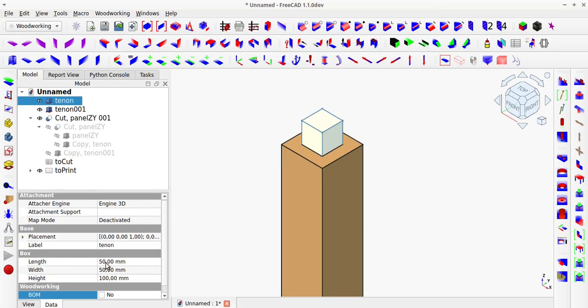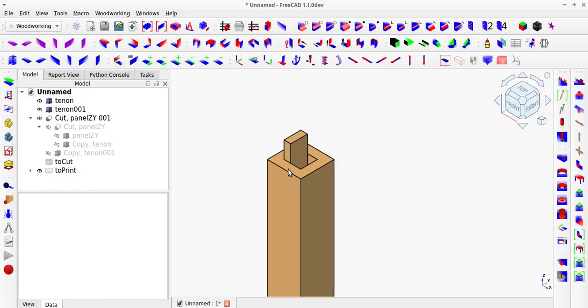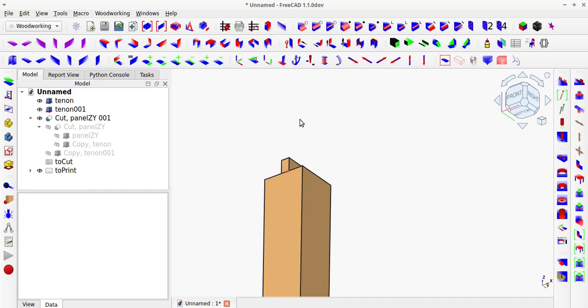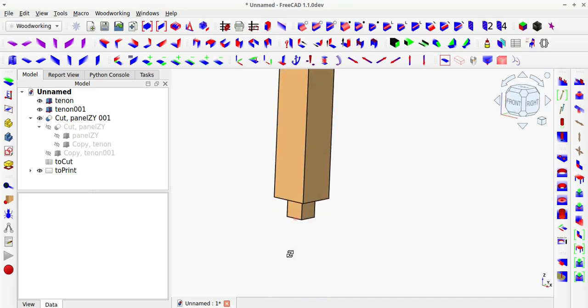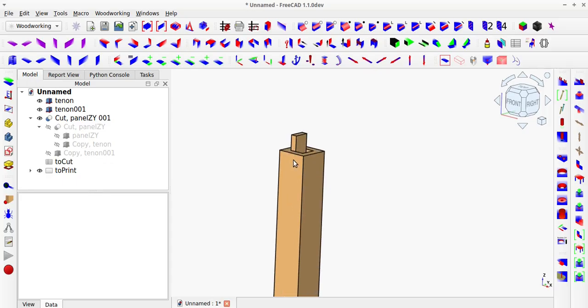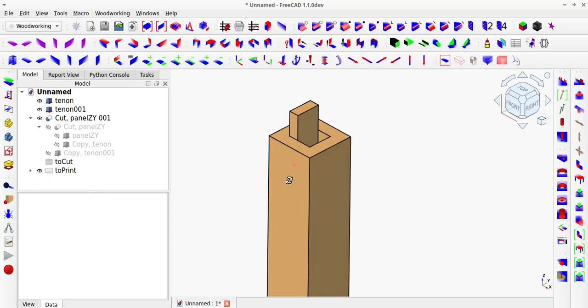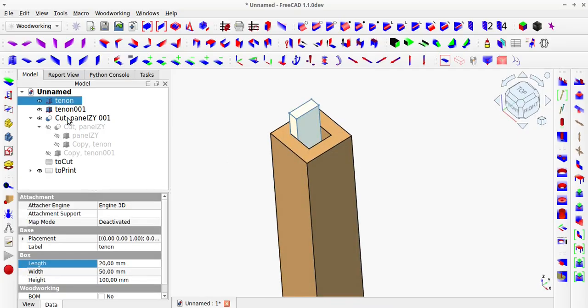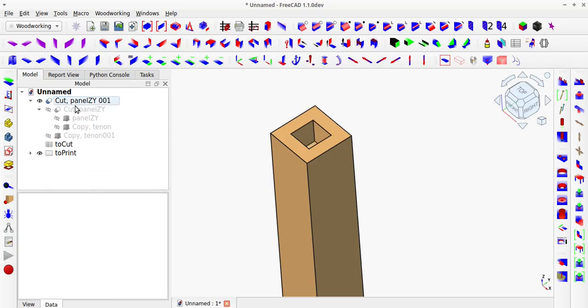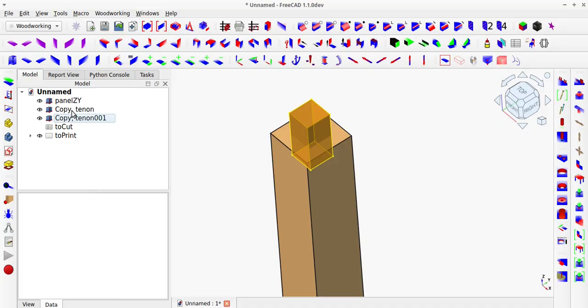The previous version of the tenon was non-parametric. This means that any changes required deleting all the tenons and recreating them. This process is quite quick, so this isn't a problem. Non-parametric modeling is much faster because it doesn't require recalculating the entire model for every minor change, and doesn't cause errors when elements are deleted. However, you can also create a parametric version of the tenon as a dowel.